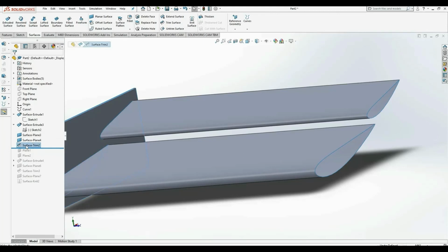And the only other thing that we need to make sure we're very careful of is the trim. When we trim that aerofoil section out, it will only allow us to do a trim on one aerofoil at a time, so we need to make sure we add an extra trim to cut out those extra pieces on the second element, because this point is still valid. So hopefully that helps you as a guide as to how to make the dual element aerofoil.